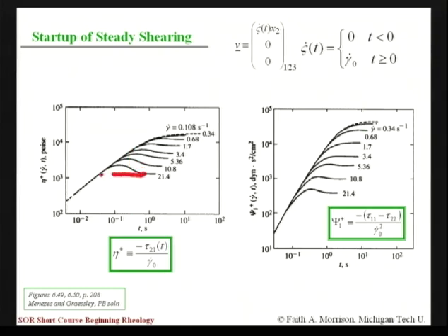And in fact, there was an overshoot. This is called a shear stress overshoot. This can be quite pronounced. Some materials have enormous peaks in shear stress overshoot. And that's flow memory happening. We're going to see that when we get to better constitutive equations. So the overall answer is, when we look at the details of what the Newtonian constitutive equation predicts, it fails on the normal stresses and it fails on the time effects.